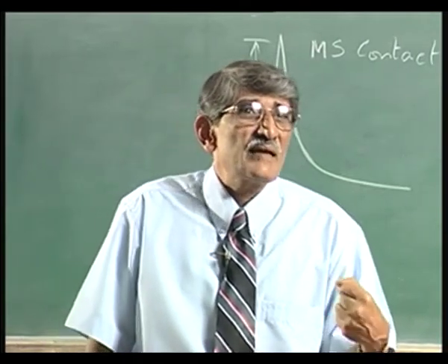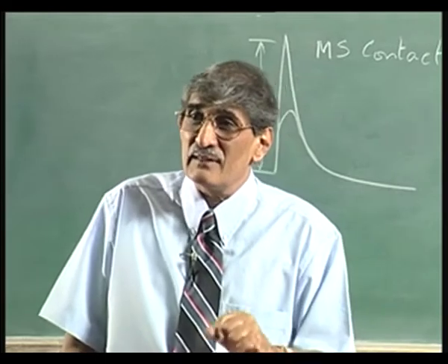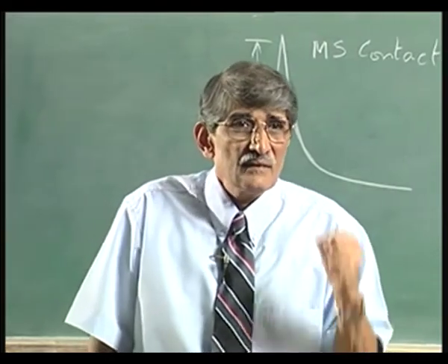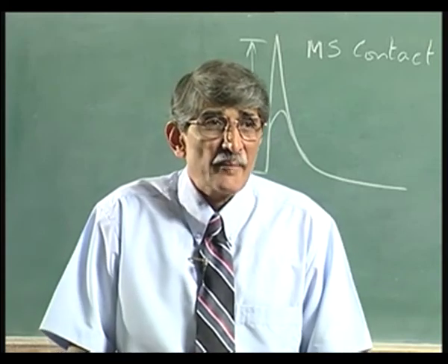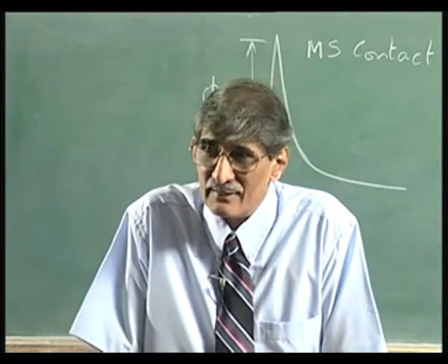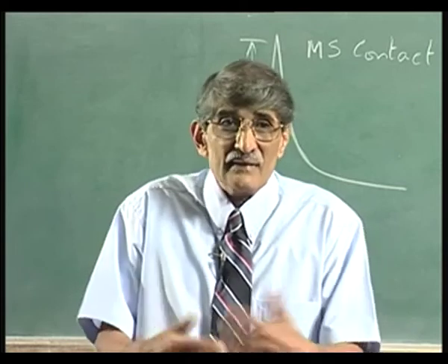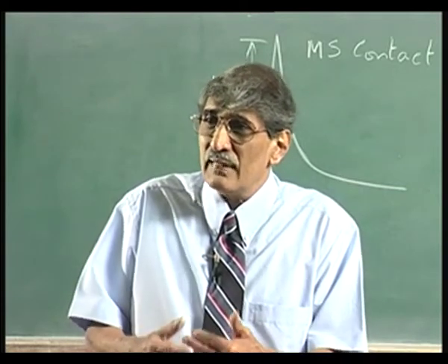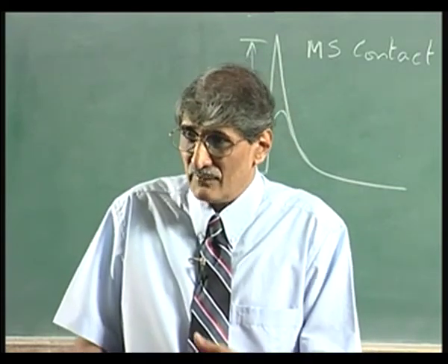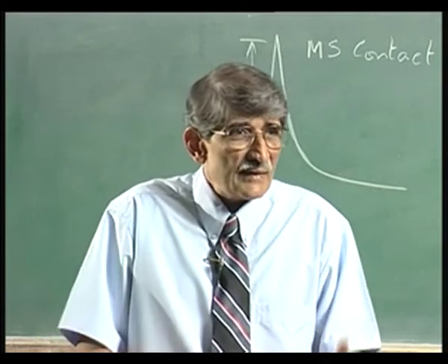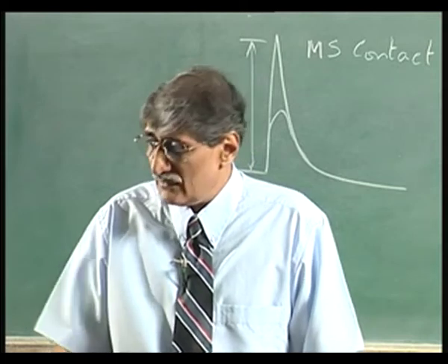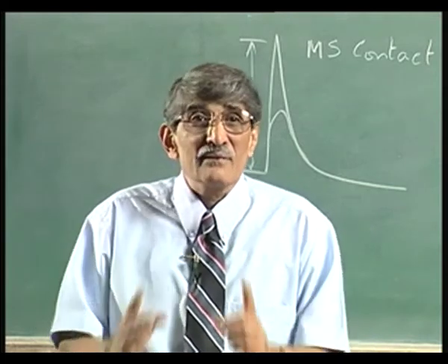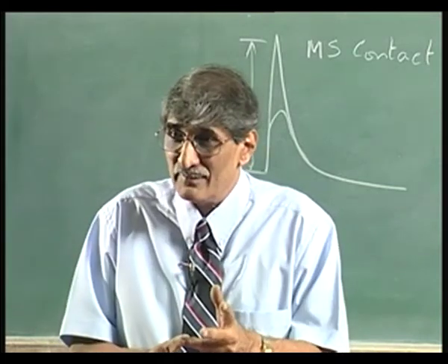So, you want to make a field effect transistor, that is where the difficulties are in materials like gallium nitride, silicon carbide, etc. Same problem is present in aluminum arsenide. When you go to AlGaAs, when you go to higher and higher x, wider band gap, barrier height more, difficult to make ohmic contact. So, that is what I am trying to point out. So that is the second problem.